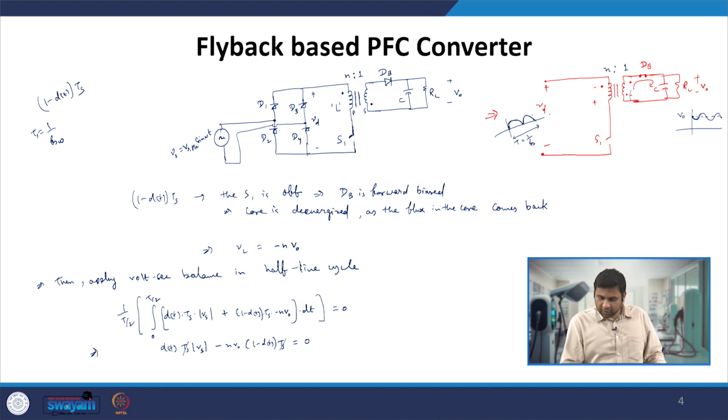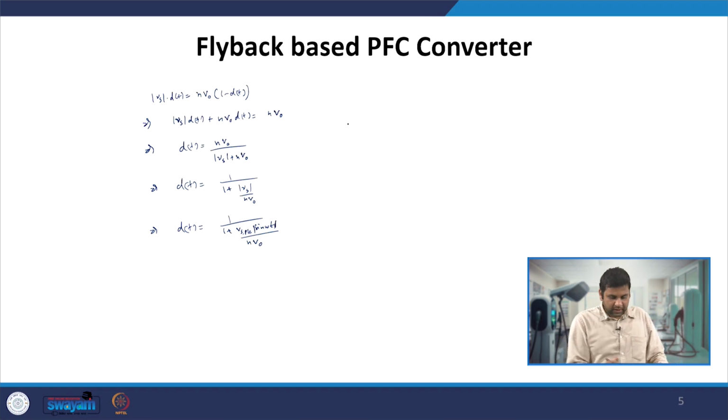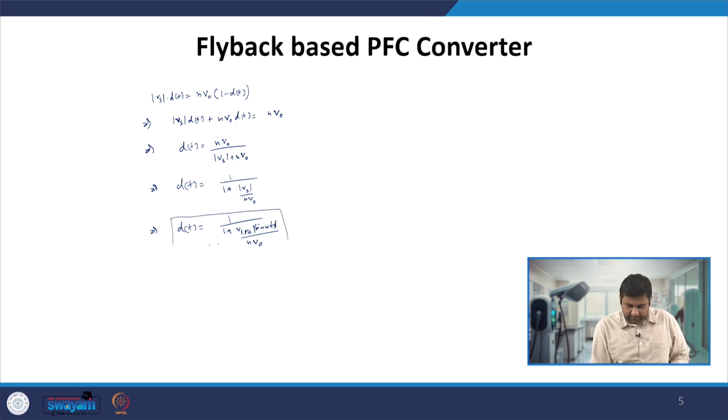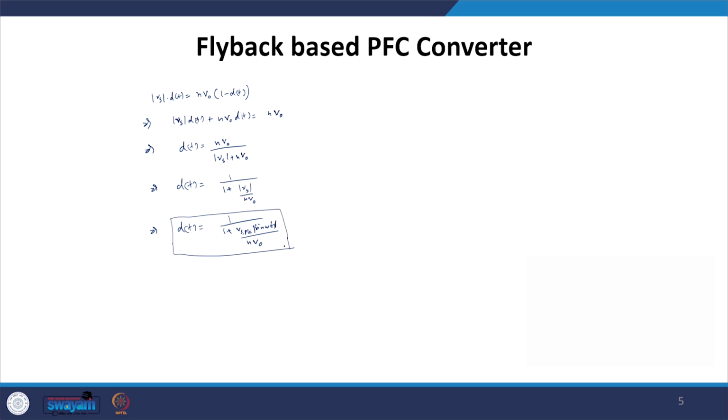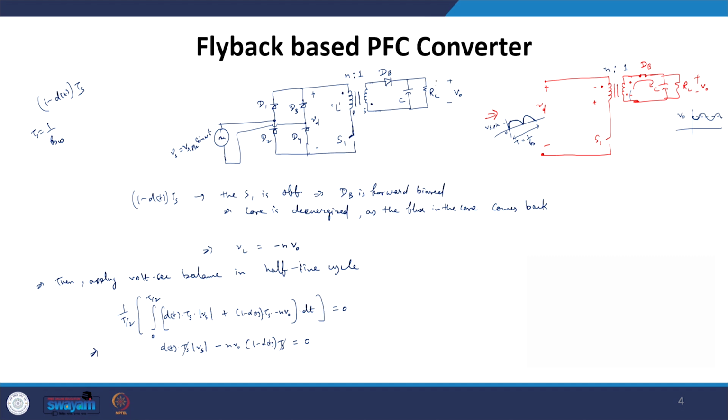So, now from this rectified voltage which is going between 0 to Vs peak, from here till this point we are getting just by ensuring that this S1 switches in with a duty ratio, that means a fraction of the period in the switching period, by this particular variation. Now if we vary this particular duty ratio, we get the constant output voltage.